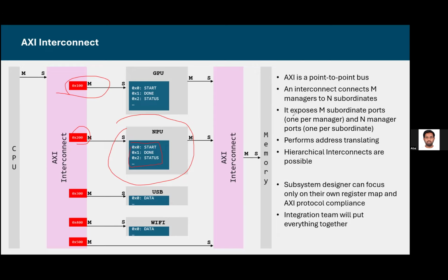On most boards, you talk to the processing system, and the processing system will talk to the DDR for you, right? There will be some MAXI port somewhere, if your SoC is Xilinx, to which you can talk as a DDR. I will not be covering that, but we will be covering an example where we interface our systolic array to the memory through a bunch of connections. So you can probably get some idea from that. This basically differs from use case to use case.